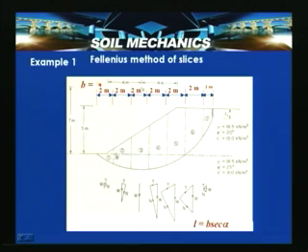Let us assume that the slope is divided into 7 slices, 1, 2, 3, 4, 5, 6, 7, with these horizontal widths for each slice. The circle is located using the procedure we have just discussed, with 4 meters and 4 meters as the horizontal distance. So, this is the central line, and with that point, and when this angle is about 133.5 degrees, this particular surface is located.